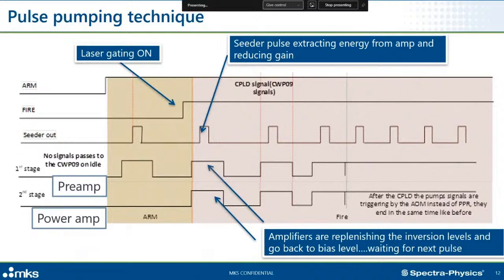The pulsing of the pump charges the fiber. But when we stop the charging, we don't completely stop it because the fiber gets discharged, so we maintain the inversion by keeping the current very, very low once the fiber is already charged. And this is what we call the biasing.